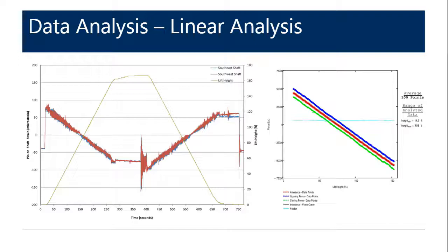For this particular case, the seated imbalance is 55 kips span heavy per end and negative 69 kips counterweight heavy when fully raised. This is in fact the intended balance condition for this particular structure, but is a perfect example of the linear behavior of the balance change as the lift span is operated.